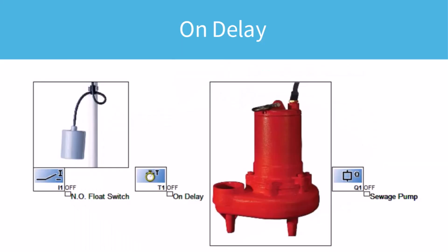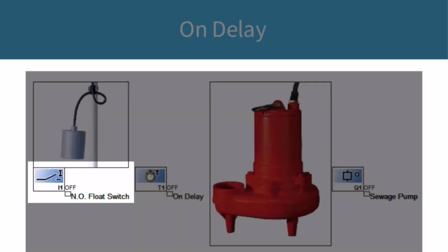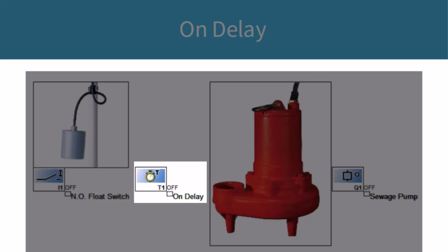Smart Relay simulation software is used to demonstrate operation of the circuit. Switch I1 is the normally open float switch. T1 is the timer, and Q1 controls the pump.